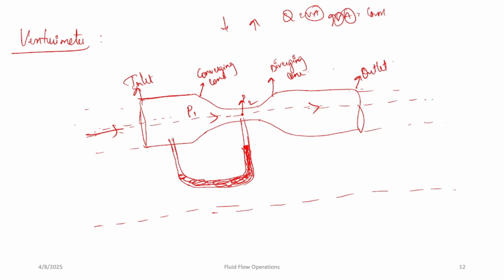The fluid slows down in the cone with a smaller angle, that is 5 to 7 degrees, where most of the kinetic energy is converted back into pressure energy. Because of the cone and the gradual reduction in the area, there is no vena contracta, and the flow area is at a minimum at the throat. High pressure and energy recovery make the Venturi meter suitable for applications where only small pressure heads are available.